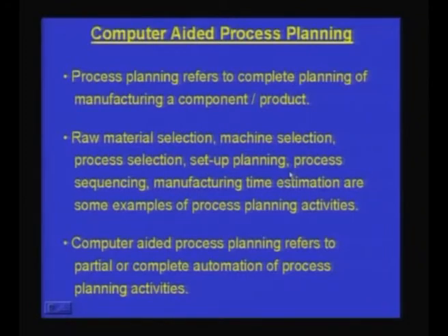If there are a number of operations which have to be carried out on a part, the sequence is very important. It not only has a cost implication, it also has serious quality implications. So, that is also a part of process planning, and many a time you have to estimate manufacturing time a priori, before you actually go for actual manufacturing.